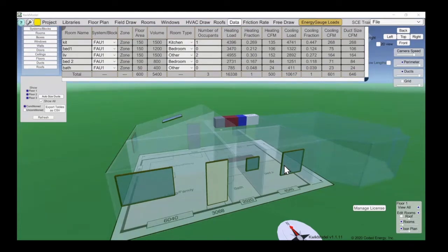But the important thing was we had an airflow and a static pressure from the furnace, and we needed to ensure that we got that airflow, that 601 right here, because if that number goes down, our capacity goes down and our air conditioner may not work as well and may not perform like we want it, okay? So we're going to size our ducts to ensure that we get at least this 601.